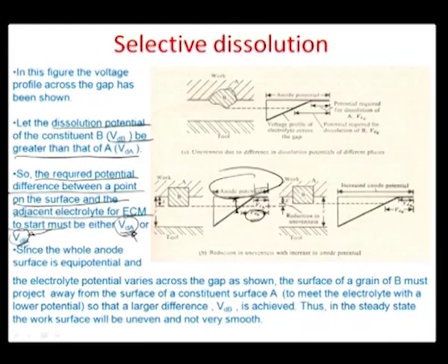So, this would result in an auto roughening, because the phase B would get dissolved away only when the voltage that it meets with is VdB. And as you see from this particular potential trend here, the effective anode potential is a smaller value, VdA, available at the surface, and this is a linear drop, of course, because this is an ohmic drop. And so, therefore, the available potential nearer to the tool surface is more in comparison to that away from the tool surface. And so, VdB will never get dissolved away at the anode surface or the workpiece surface.